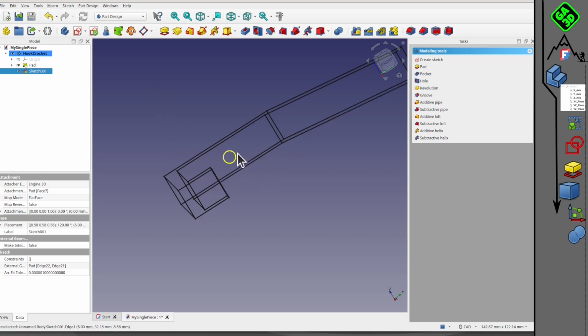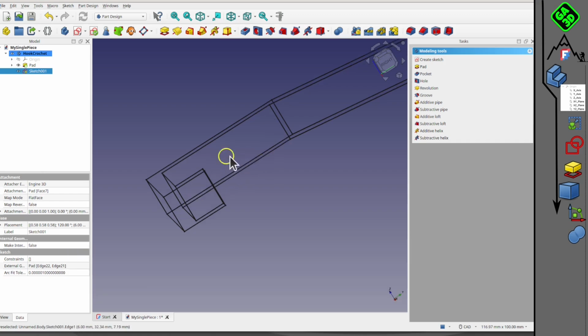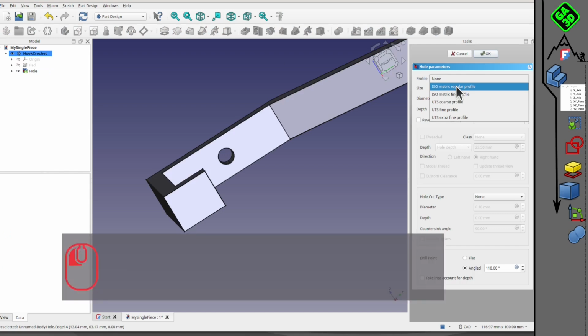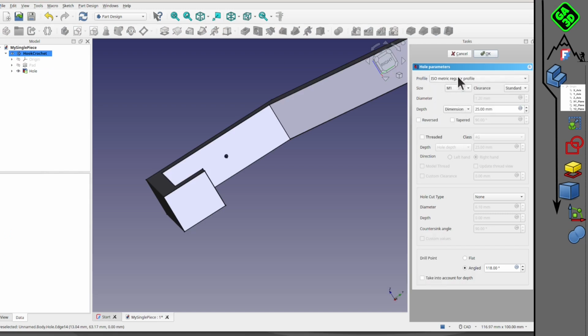So you select your sketch, and then you click on the drill tool. Then you have direct access to the different standards. I still work with ISO screws, and now I'm going to make a passage for an M3.5 or M3 screw. So you see it creates my piercing directly through my hook.